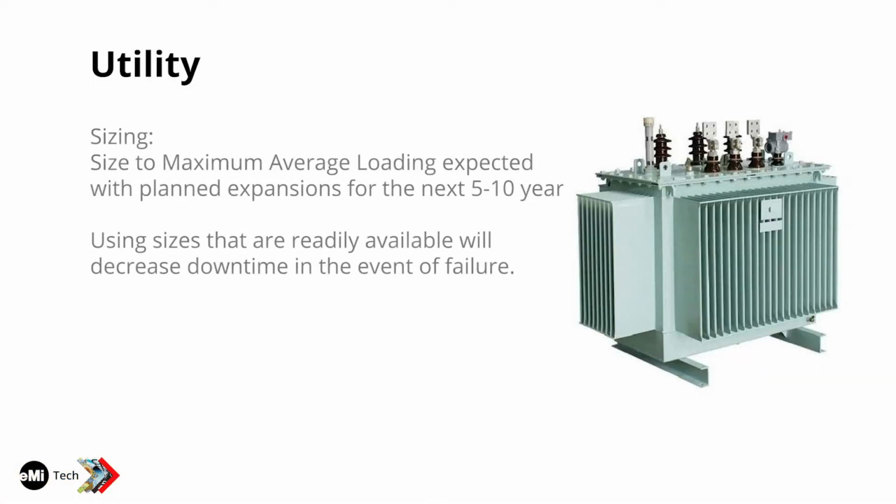It's totally fine to do that. And in fact, that's what we want you to do. We want you to size it to the maximum average loading expected with the planned expansions for the next 5 to 10 years. And this would be advisable if you can use sizes that are readily available.